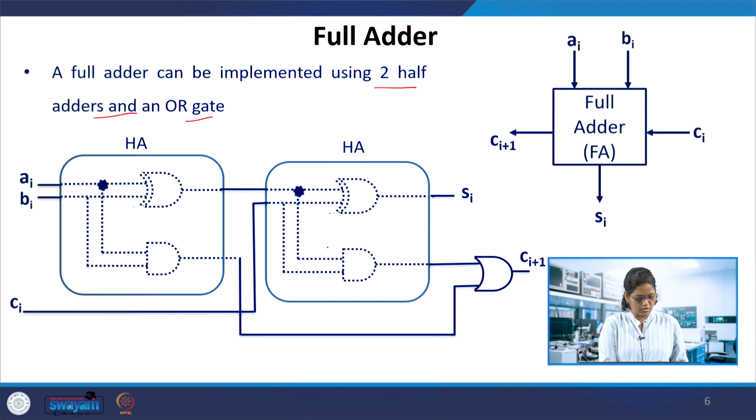So this is what we had done already. Here A, this is a half adder, and I showed you that C is taken with the XOR operation to get the sum, and two half adders were shown in the previous circuit. Now we will analyze this by changing the circuit to NAND gate inputs, to make it uniform and find the gate delays.